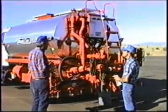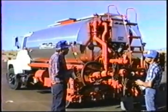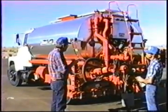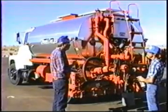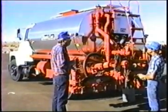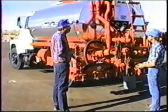Once we've got the tank dried out that way, then circulate the spray bar. You'll need to circulate it now when the tank is low, so that as the material circulates through the spray bar and pushes the water that's in the spray bar and the piping into the tank, it has room to boil out after it gets into the tank.